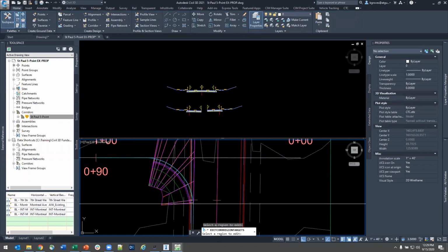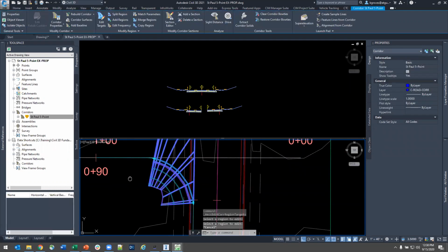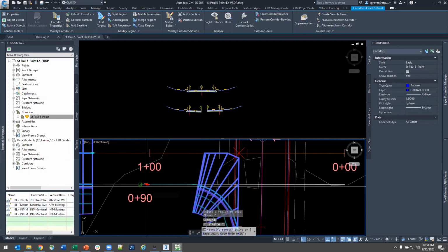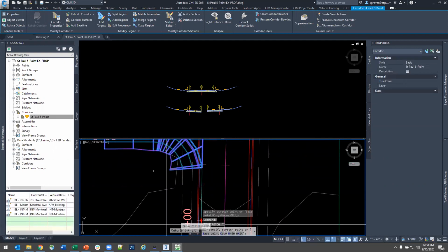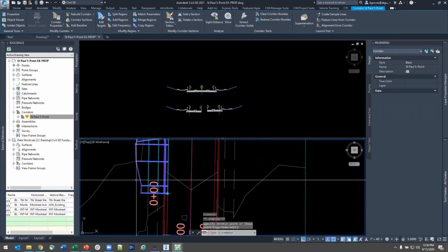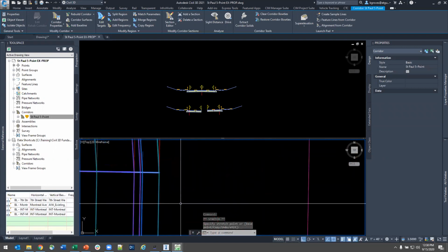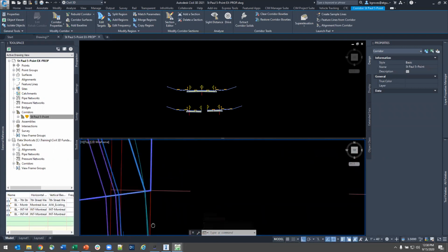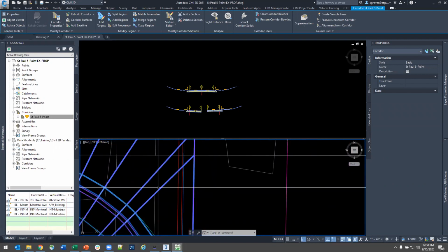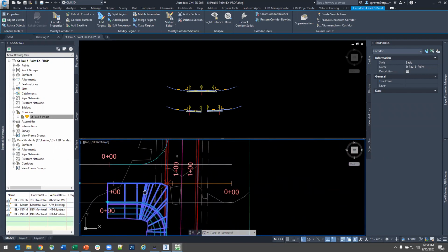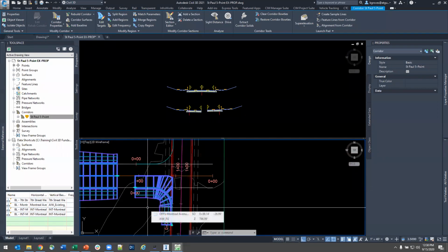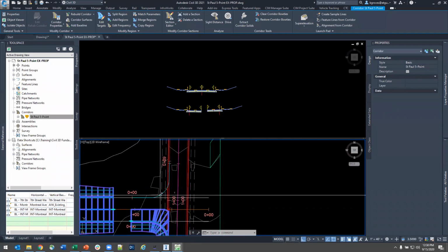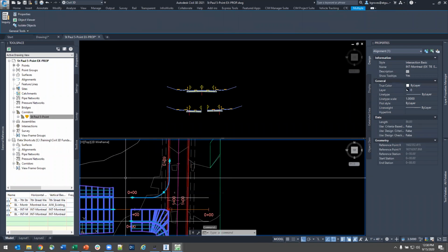Now that I can say, okay, this is looking a lot better. If I want to, I can go ahead and just bring this region to the very extents of my roadway. And now I'll see that it's only as big as it needs to be to make all this stuff happen. All right, I have a baseline. On the left side of my baseline is my curb. So let's take a look at now this northwest quadrant.